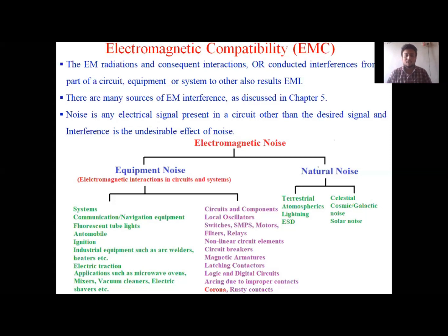But please remember, there are some devices which are very sensitive in reality. So even the small power received by the cable, which we are using to connect the components in the circuit, acts as a Hertz antenna. That particular power is capable of destroying the device. Sometimes it may happen, depending on the sensitivity of the device. Some devices are very sensitive. So if your device is very sensitive, even a small power received by the cable can damage the entire circuitry and can affect the performance of the system significantly. So selection of the cable is also a very, very important thing.